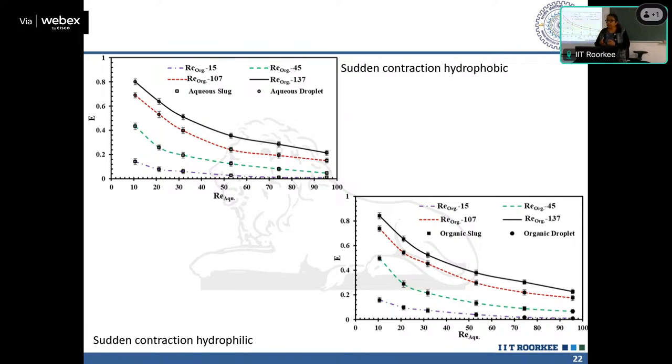So if you don't have any circulation or disturbance, it eventually becomes slower. On top of it, the limitation of the molar ratio is also playing a part. That is why these are not favorable conditions to carry out the extraction. And this is true for every other geometry. There is absolutely no effect of geometry in these operating conditions.